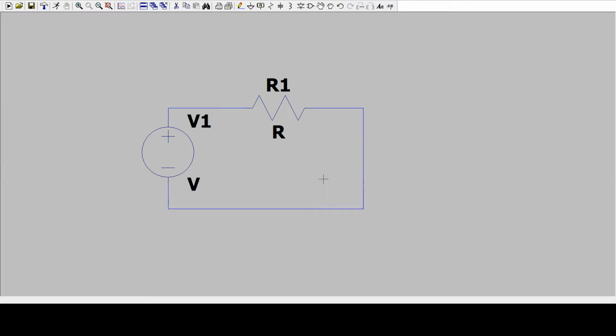So we have a circuit, probably something similar that we've seen in class so far. But something that's different that will become apparent why we do this in just a couple weeks when we talk about nodal analysis methods. Remember that when we talk about voltages, we talk about voltages across elements and currents through elements. Voltages across because remember, this is a potential difference, meaning that it has to be relative to some other value. So in circuit design, we create something called a ground, and the ground is a reference, usually of 0 volts. So we always need to reference our voltage sources to something, and 0 volts is easy. If we look across here, because there's a resistor here, and because voltage equals current times resistance, we're going to have a potential difference between these 2 points because of the resistor.